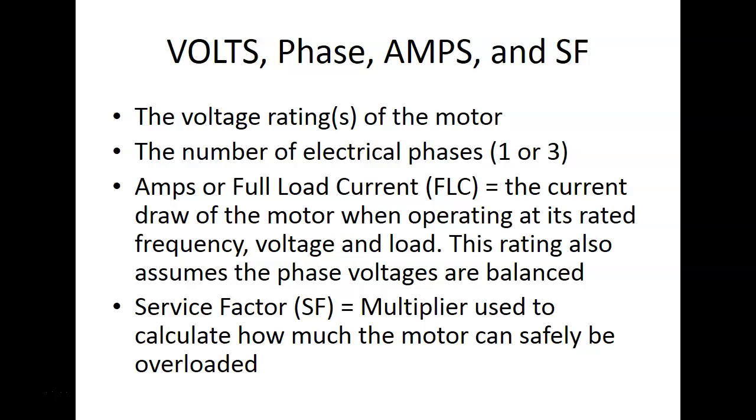Service factor, multipliers used to calculate how much the motors can safely be overloaded for short periods of time. So our service factor on a motor is 1, which means you can't do what with a motor. You can't make it pull more, produce more horsepower than what it's designed to pull. Everybody okay?